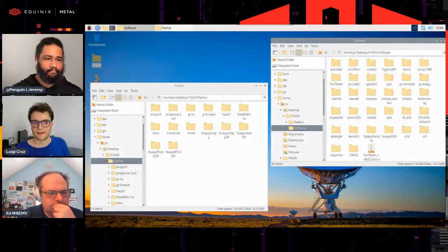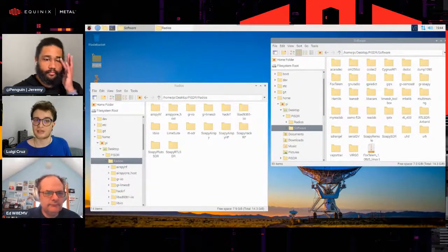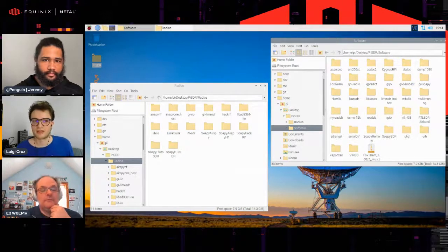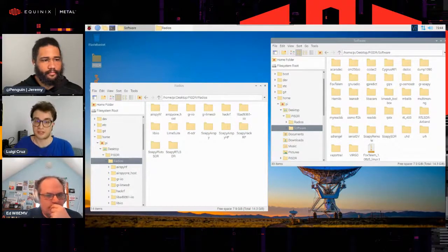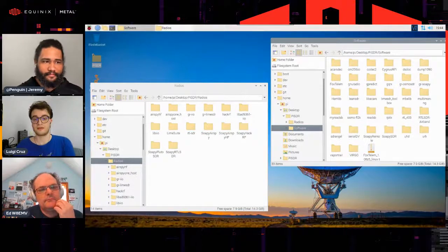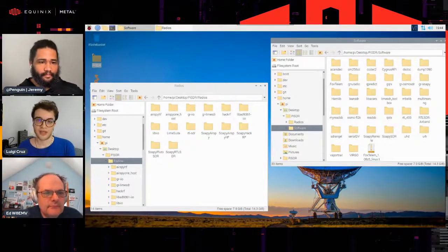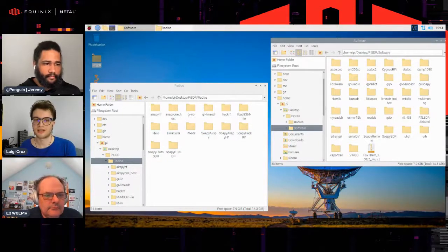But there are some bleeding edge satellites like the NOAA 20 that transmits in the X-band at 250 meters per pixel resolution, so it's big. The file sizes are also big. You need an automated dish of 3 meters or larger to receive the signal. You'll need a specialized SDR to quantize the signal and transmit it to your computer. And you can't do it in real time because there is too much data to process. So you need to record this on a fast drive and later decode offline.